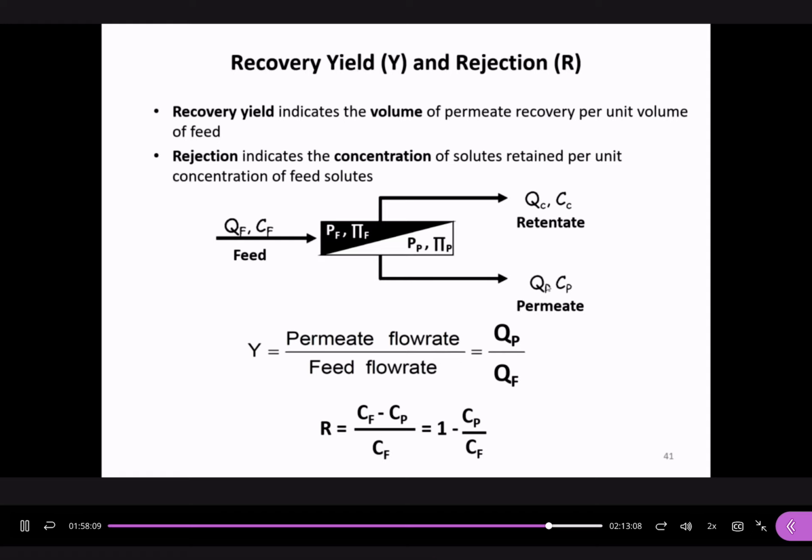So at the desalination plant, we have a post-treatment step. You add useful minerals, magnesium, fluoride. Fluoride is very important for our bones, for teeth. So you have to add these minerals back into the water. Typically you can find all the information from the membrane specifications: operation range, applied pressure range, the yield, rejection for different salts.